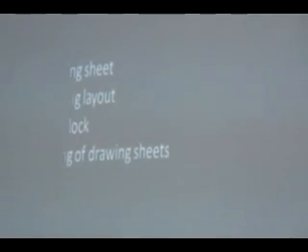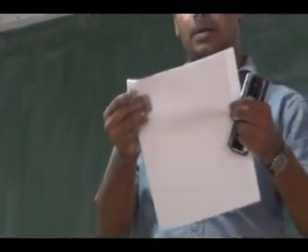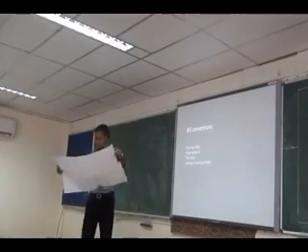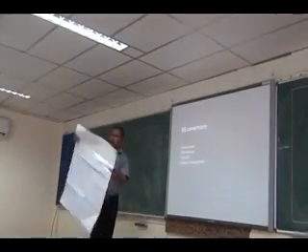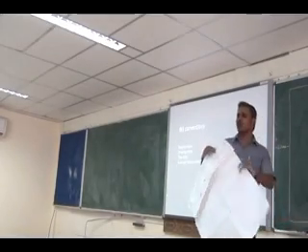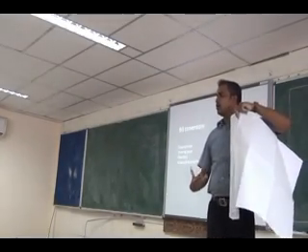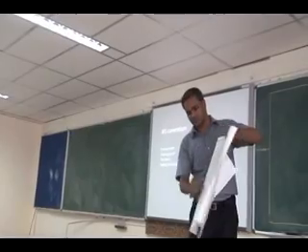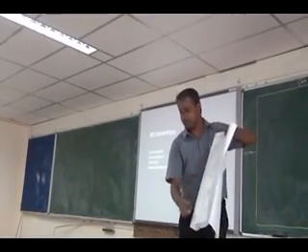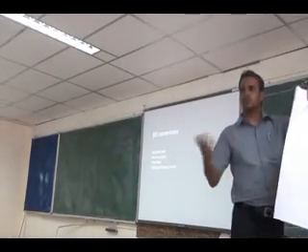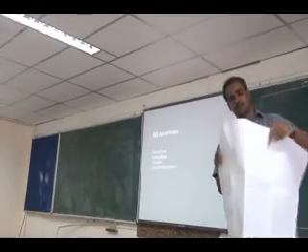I can fold it like this to match the left margin, left layout. After folding, the title block and the drawing detail should visibly come to the top of your folding. This is the title block I have for this company. These details should be visible in your file while you are running your file, on the top. In that manner it will be folded.